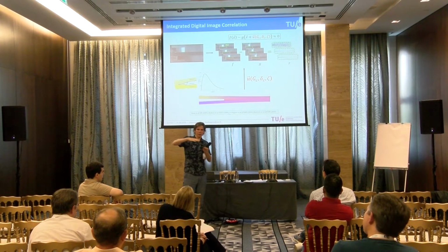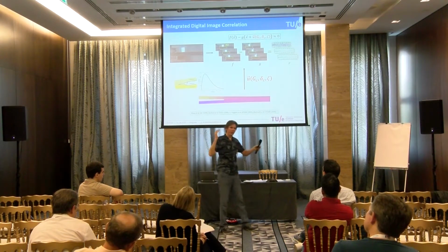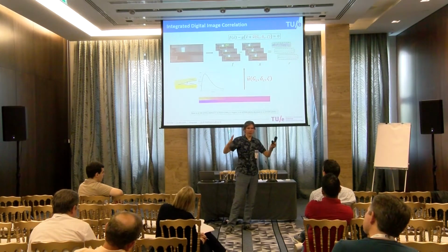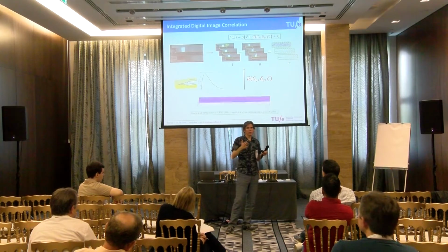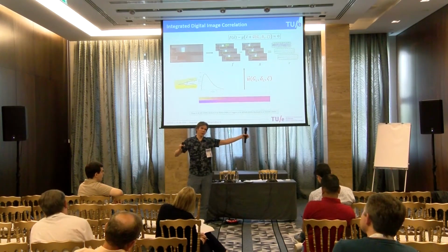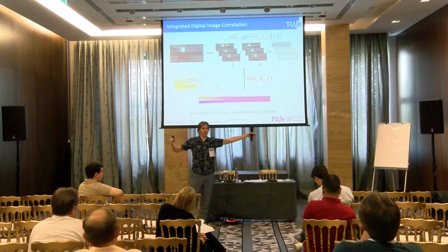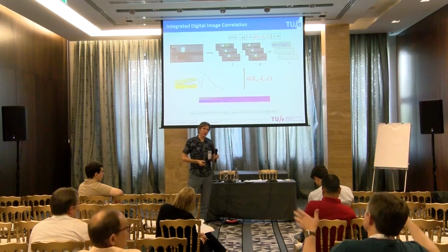Initially the process zone builds up, and for such a test you would typically like a process zone that is stable and moves along. But we don't really need it, because we can also identify when the process zone just becomes bigger and bigger and you never see the end of it. That's fine, but it's not optimal.